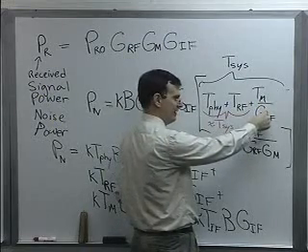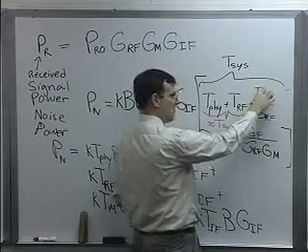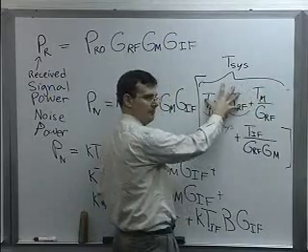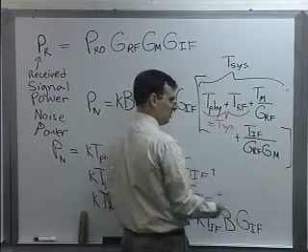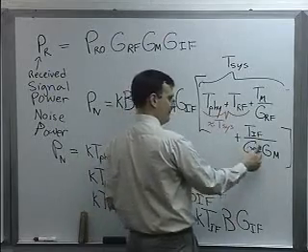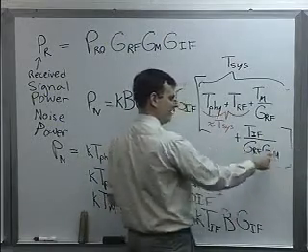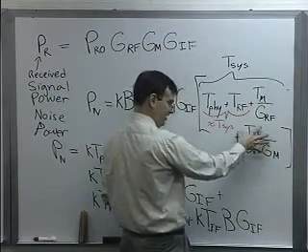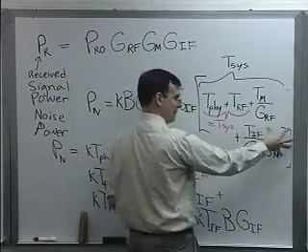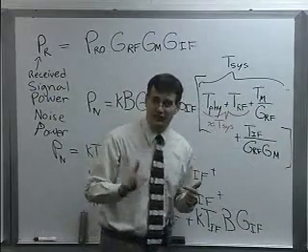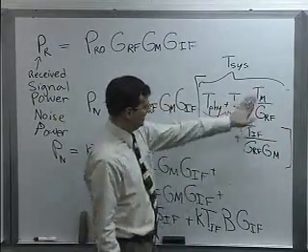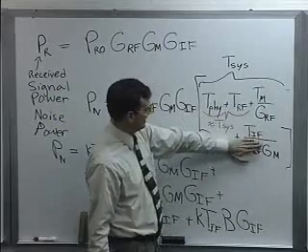in the denominator. And whatever this is, it's not going to contribute much to the total sum because it's getting knocked out. And presumably, as long as you have additional amplification, you're going to consistently knock these out further and further and further. Think of what would happen, though, if you didn't have that LNA on the front end. This term wouldn't be here. I wouldn't get G sub RF.